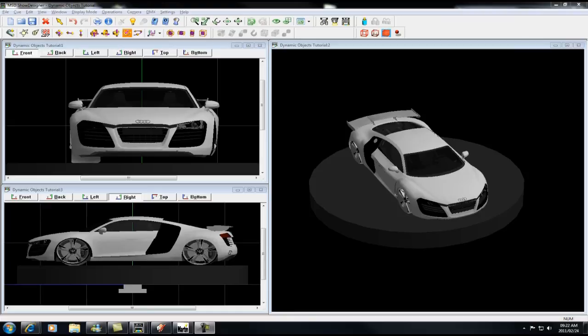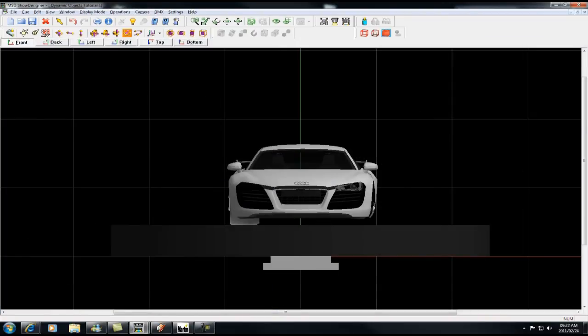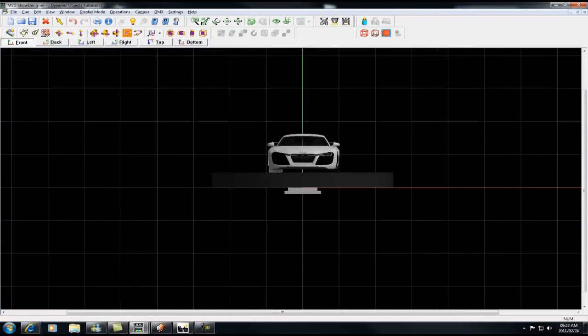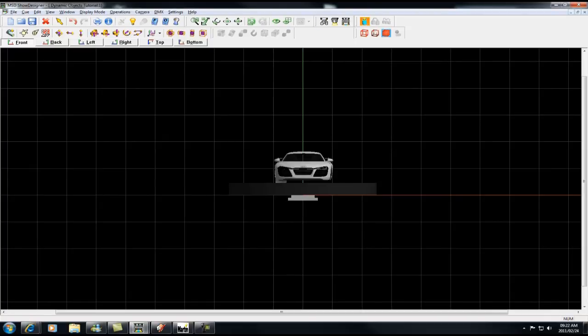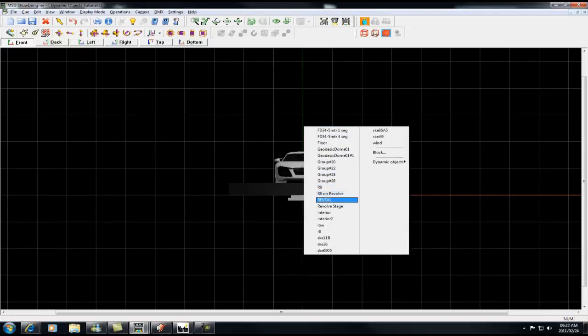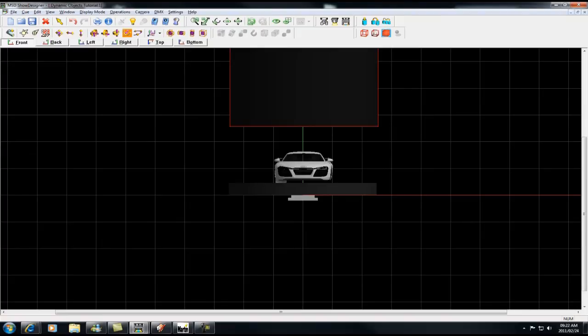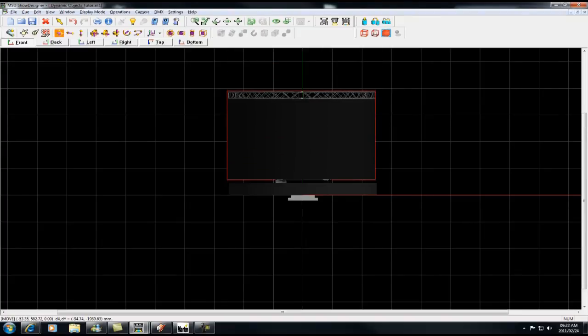The next thing I'd like to illustrate is how to go about using the Hoist platforms. Let's maximize this window. I went into the modeler and created a reveal. Let me insert that. Put that in place. It's important to know that if you intend on adding in fixtures, you need to do that before attaching the Hoist platform. For now, let me add in some fixtures.